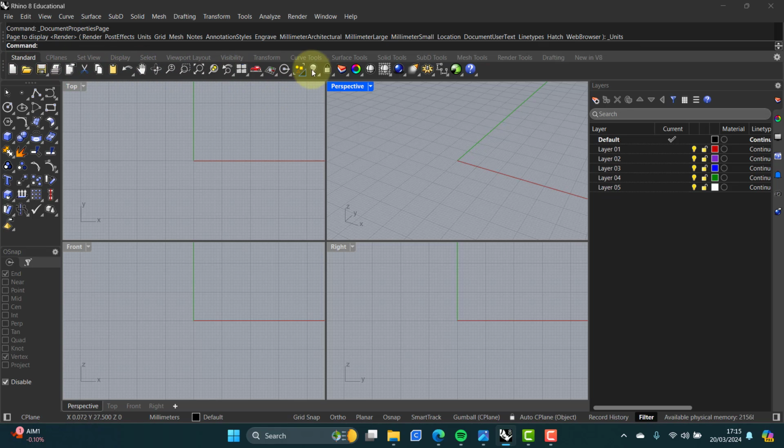Okay, so the more esoteric commands are up here, and the most often used ones are down here. Okay, down this side we've got layers, and these are really quite editable. You can move things up and down and group them as well, which is handy. Down at the bottom here we've got what I call helpers. Okay, at the moment filter is switched on. I'm going to switch that off, so none of them are switched on at the moment. Okay, we're going to start with grid snap to make drawing a bit more controlled.